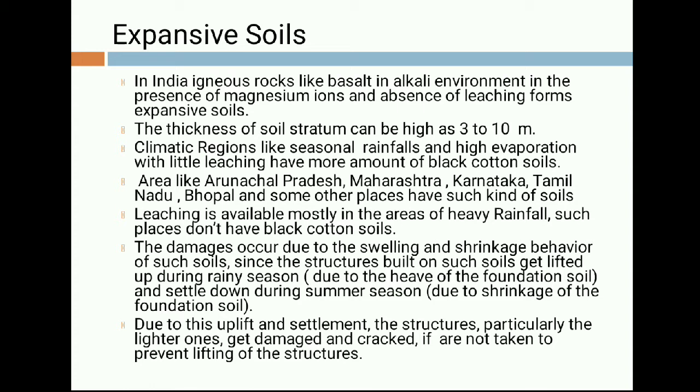The damages occur due to swelling and shrinkage behavior of such soil, since the structures built on such soil get lifted up during rainy season due to heave of the foundation soil and settle down during summer season due to shrinkage of the foundation soil. That is based on climatic conditions. In case of monsoon season, there will be more amount of moisture addition in the soil that will swell the soil, leading to the heave of the foundation. And in case of summer condition, there will be desiccation or evaporation of soil water from the soil that leads to shrinkage of the foundation soil.